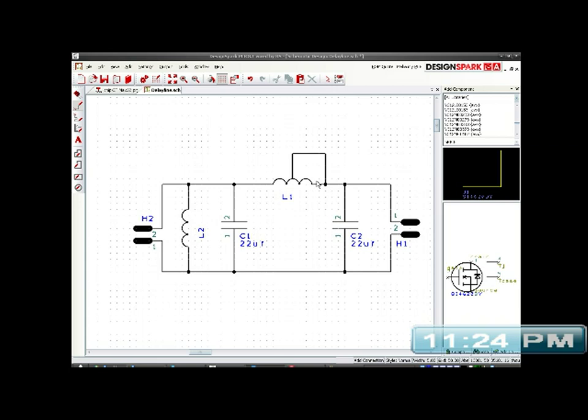So, at least, with a circuit board type, you can actually tin it and make the coil thicker if you want to reduce its impedance, so you can tune it just by adding solder to it as well, which is a lot easier than messing about. You can't exactly solder the wire onto a coil that's wrapped tightly together, because you'll join all the wires together, so that's not a good idea either. Yeah, so we're only talking about a few microseconds on this coil. So it doesn't need to be massive.